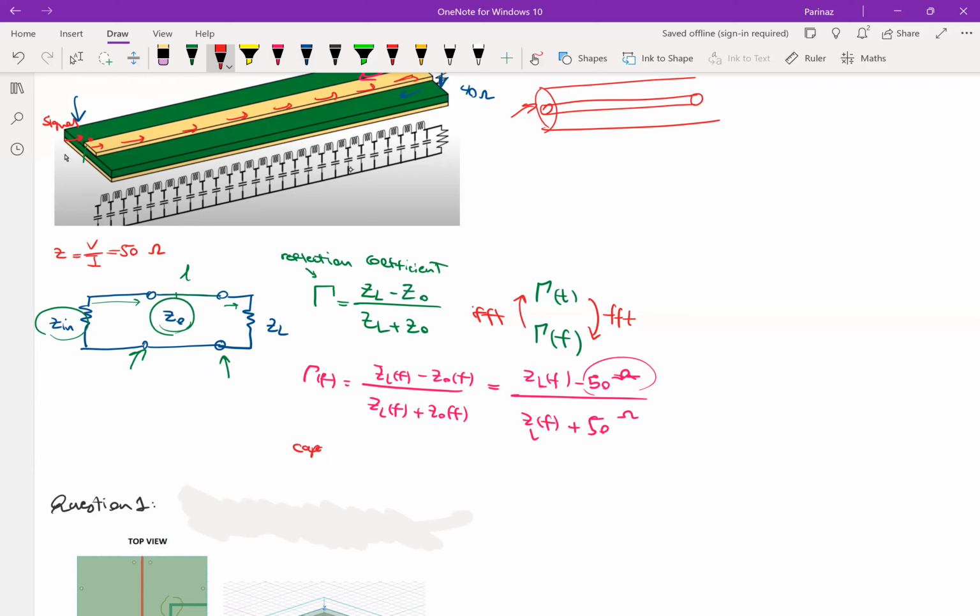If you have a capacitor, if you have an inductor, these are elements, or even more complicated ones, like a chip or BGA or whatever you have. But the simplest concepts that you might be familiar with are the capacitor and inductor. The Z of a capacitor is 1/(j omega C). The impedance of an inductor is j omega L. Simple terms, but it can complicate the reflection coefficient.